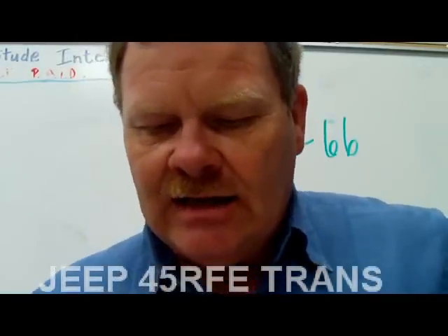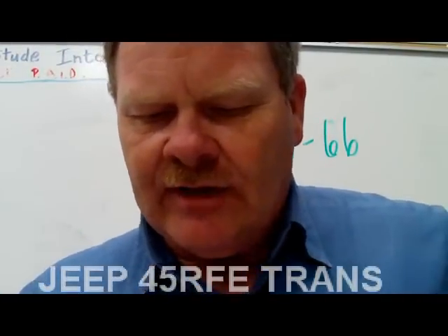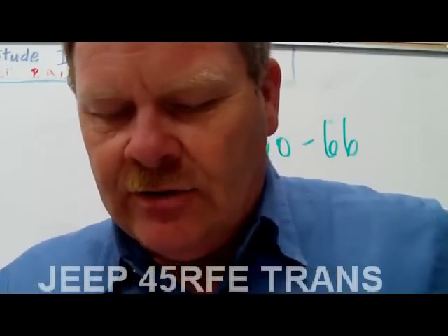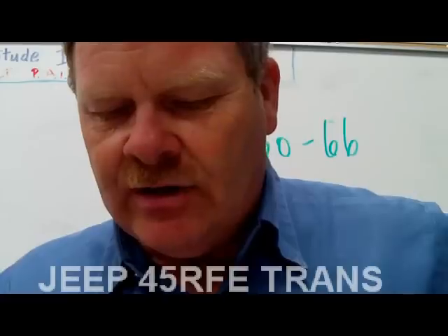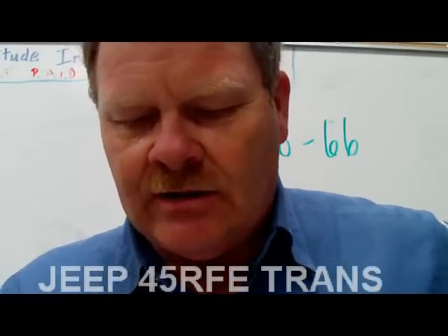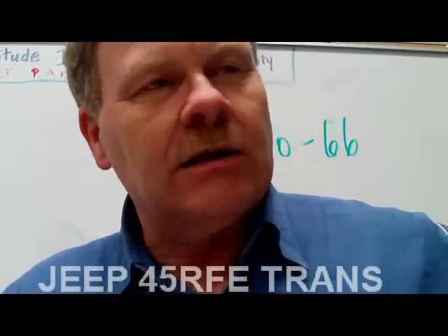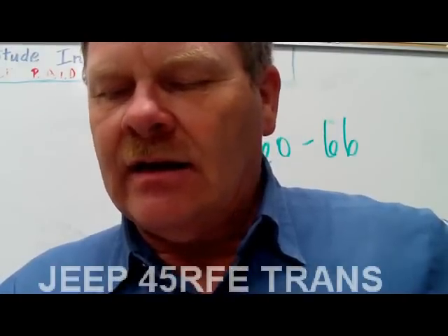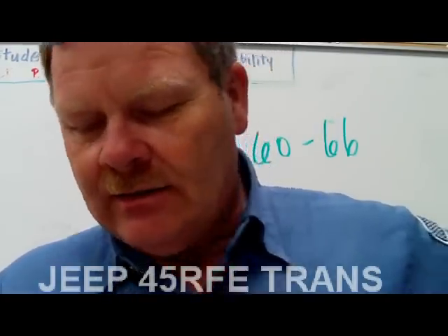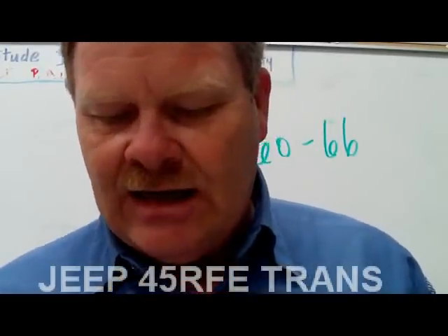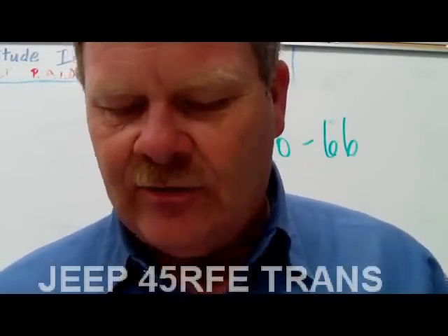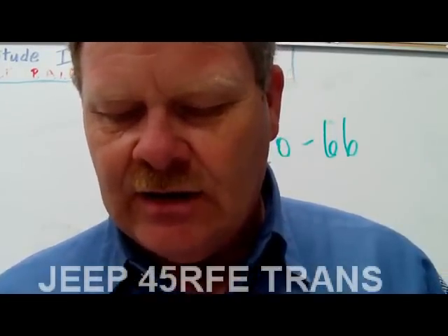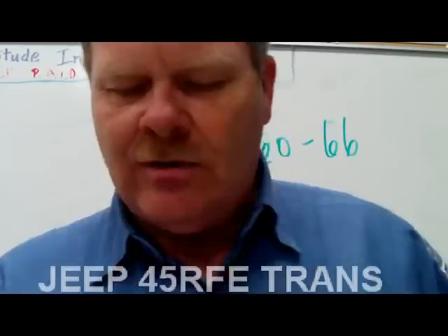All right, so you've got a transmission case label that includes a part number and an identification code on this 4RFE, and the number stamped into the pan rail. It includes the plant code, Julian date, year built, sequence number, and the part number. Proper identification of the transmission is important if you're going to order parts or seek technical assistance. Seeking technical assistance is what the dealers do whenever they run out of ideas and have to call the people at the hotline. It was designed for use with the 4.7 liter V8 in the Jeep Grand Cherokee and the Dodge trucks. The first vehicle that had it was the 99 Jeep Grand Cherokee.